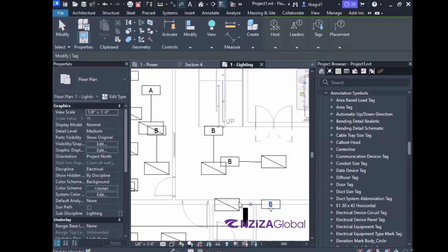But now we also need to make sure we translate this data in a tabular form, right? Like A light fixture, it is a 2x4, 120 volt, 96 wattage. When it comes specifically to photometric information, what type of color rendering index it has, what type of color temperature it has. These lights are cooler as compared to that light over there, that is a warmer light on the wall. This is a cooler light, so there will be a color temperature difference. So this is what tagging is.